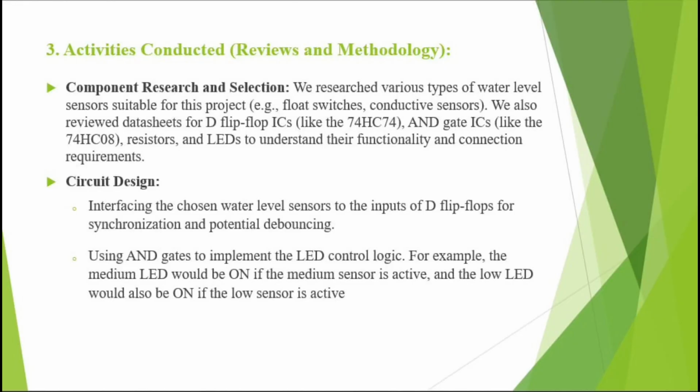Activity conducted. Component research and selection. We researched various types of water level sensor suitable for this project. We also reviewed datasheets for D flip-flop and AND gate IC, resistor, LED, and buzzer to understand their functionality and connection requirements. Circuit design. Interfacing the chosen water level sensor to the input of the D flip-flop for synchronizing and potential debouncing. Using AND gates to implement the LED control logic.